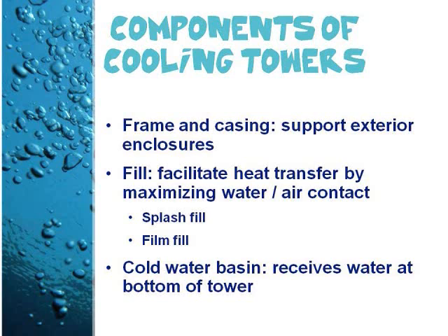Film fill consists of thin, closely spaced plastic surfaces over which the water spreads, forming a thin film in contact with the air. This surface may be flat, corrugated, honeycomb, or another pattern. The film type of fill is more efficient and provides the same heat transfer in a smaller volume than the splash fill.